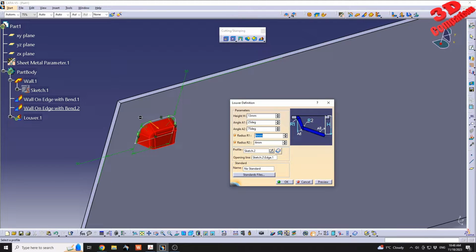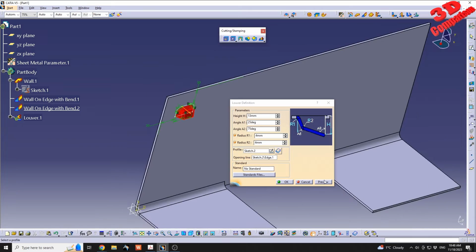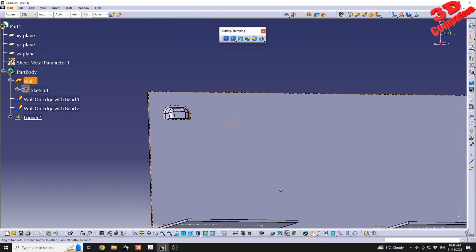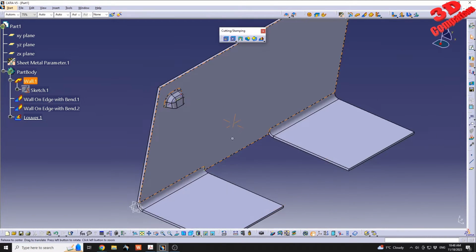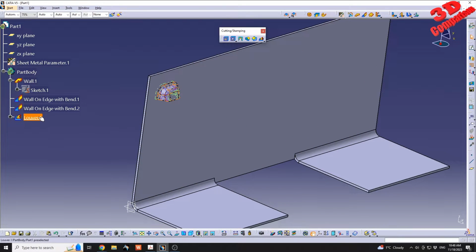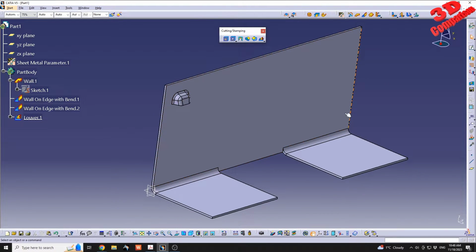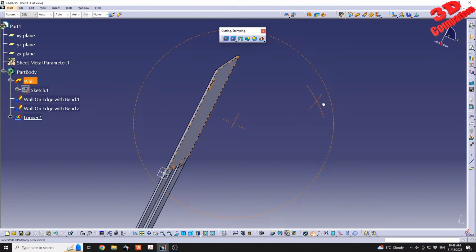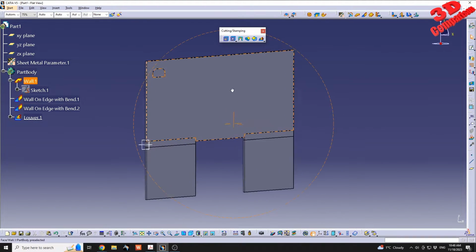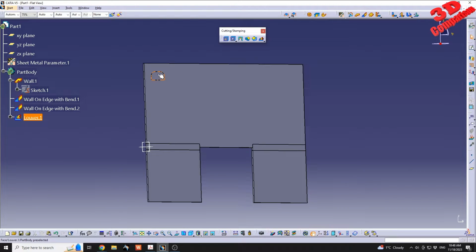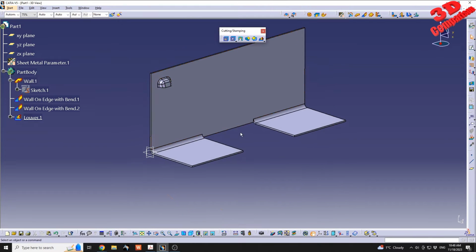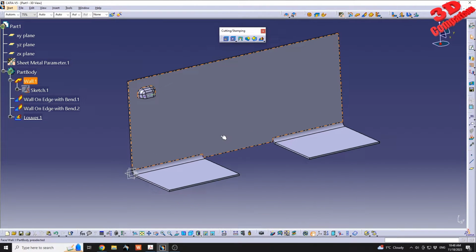If I position this inwards, now we're gonna have that stamping position like this inwards. So keep that in mind, that when you define that, you don't have the direction, but after the louver has been created, you have the possibility to do that. And what is most important is that you can also use fold and unfold in this case, but again the louver will not be folded and unfolded because this is a stamping. This will be added within a various, let's say, manufacturing operation.